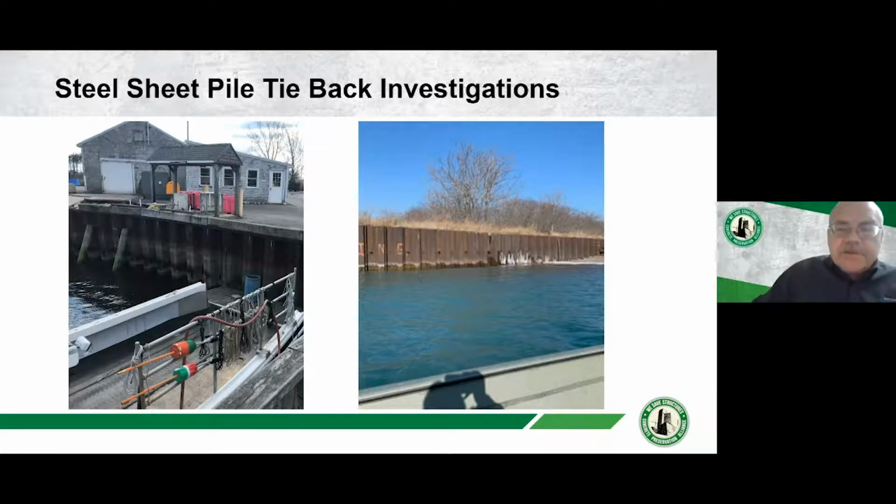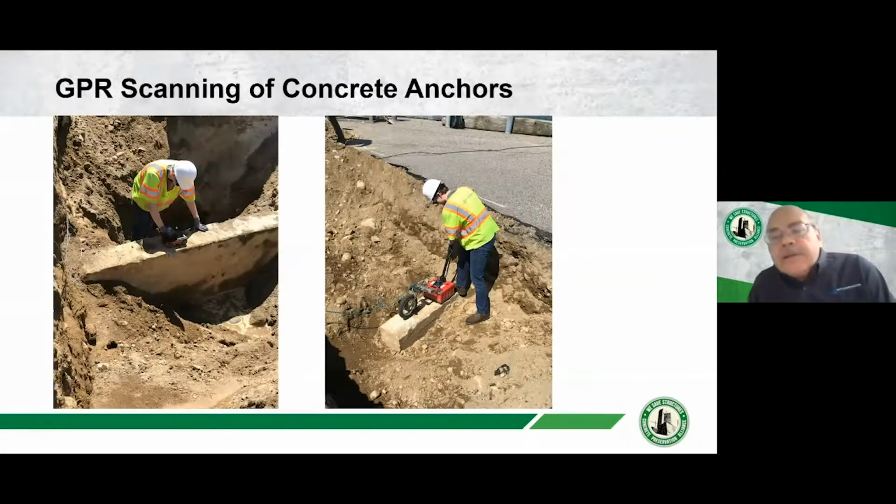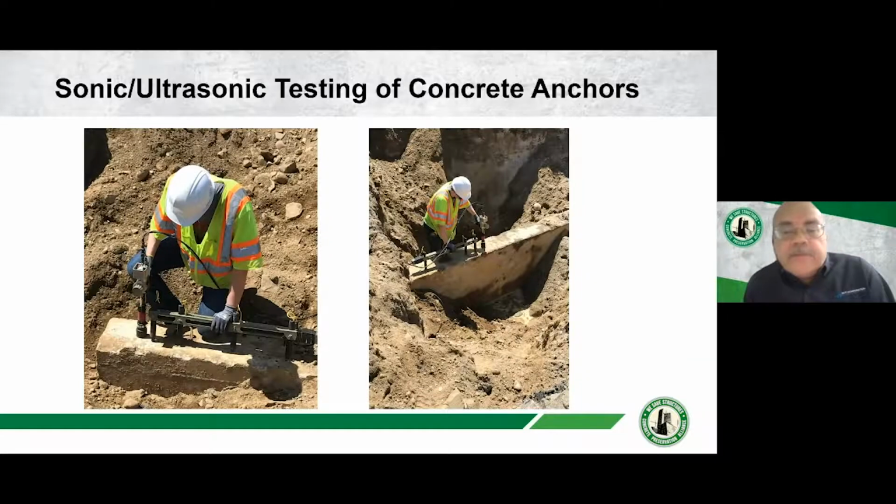is very valuable to determine, is there an anchor that is tied back to the shore to hold that sheet pile wall up? Once it's exposed, we can scan it and determine, is there rebar, what is the spacing of the rebar, what is the thickness or the geometry of that anchor? There's an example of 2 radar devices scanning that, and here's an example of our sonic system that's verifying the dimensions of the anchor, and more importantly, determining the strength of the concrete.